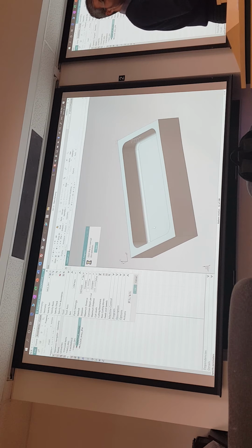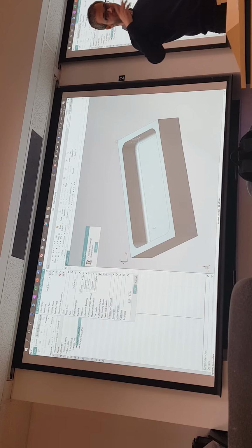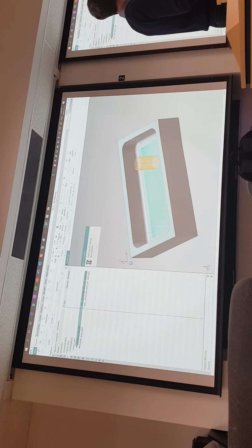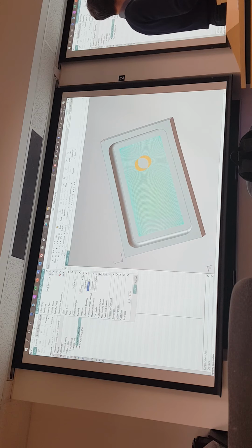That maximum distance was the radial depth of cut? That's the radial depth. Okay. But then if you're doing like facing, then it would be the axial. You have to pay attention because it's specific to what you're doing. So this is with 60 thou radial step over.